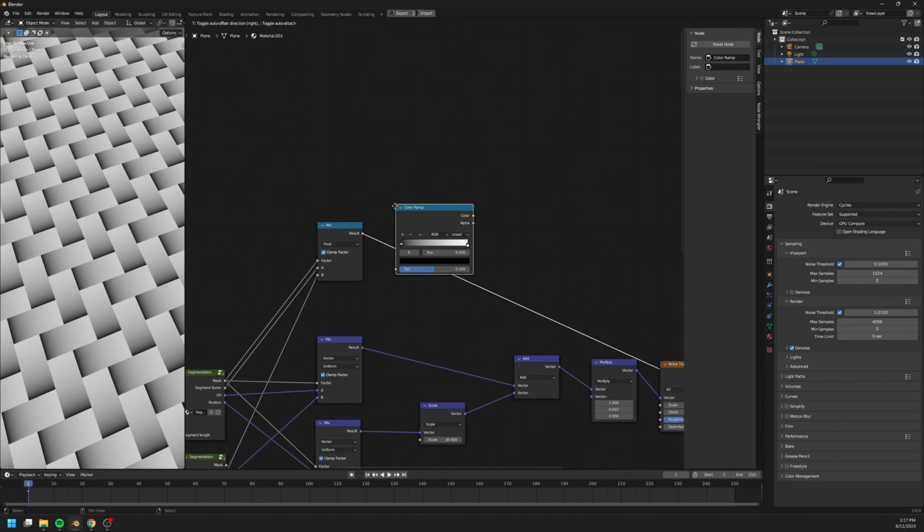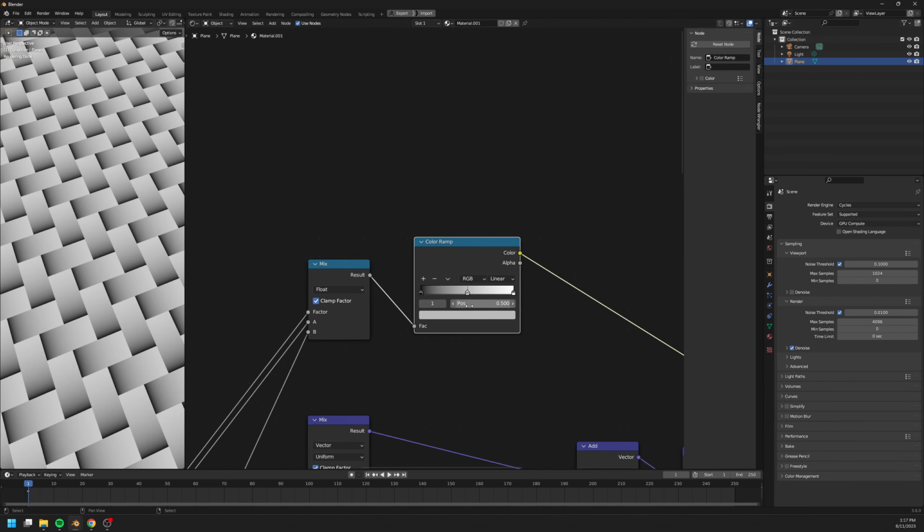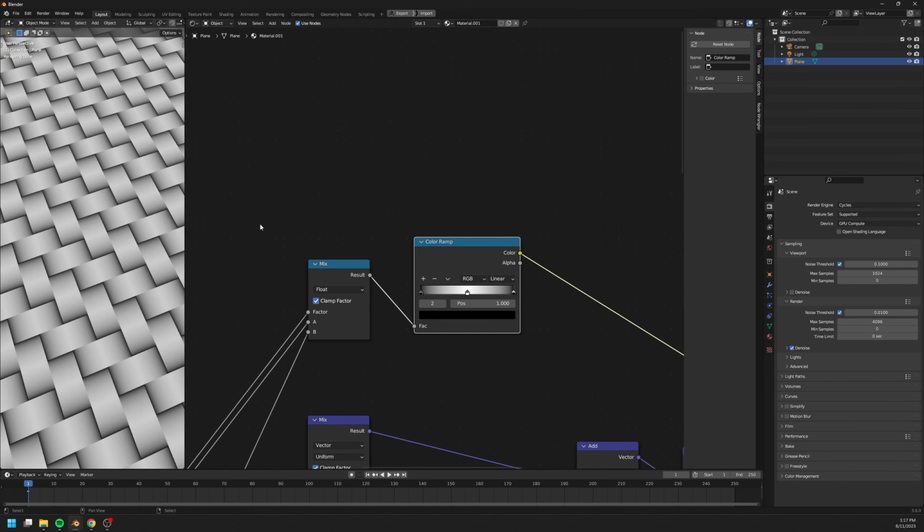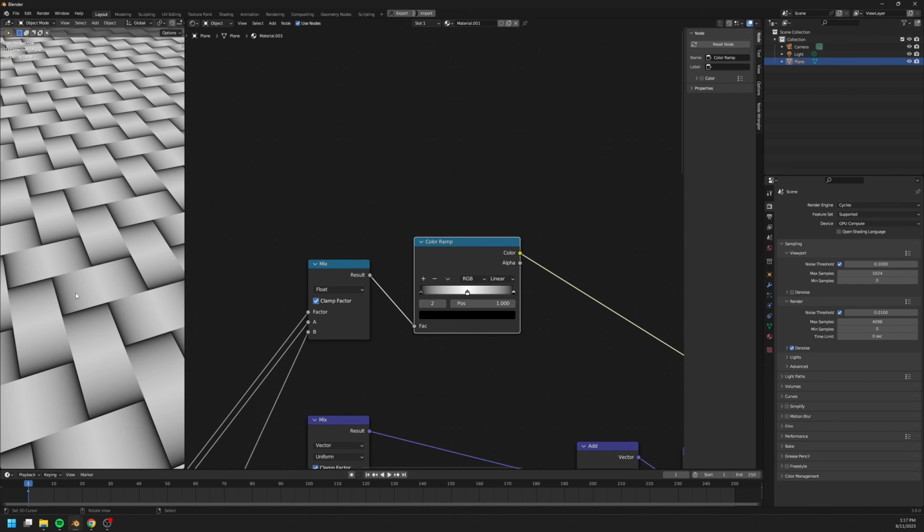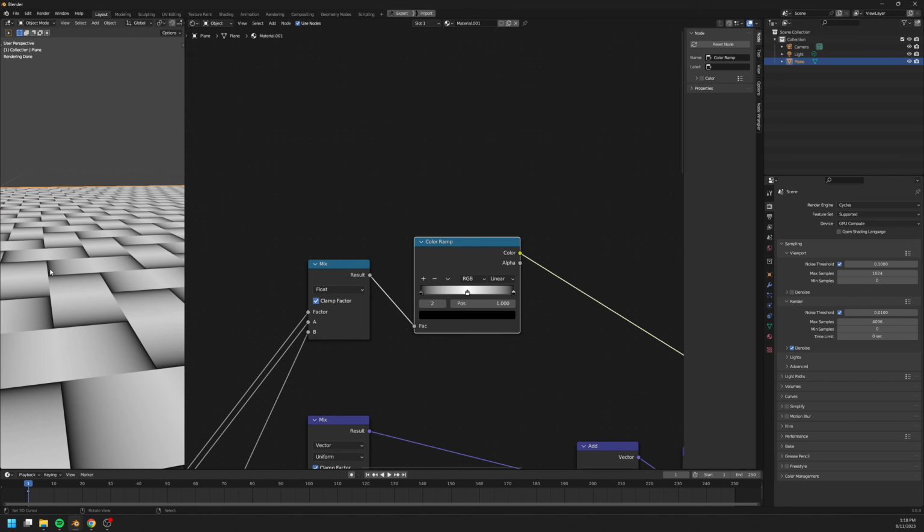And the easiest way to do that is using a color ramp node. Create another key at the exact center, and this key should be white. And set the left and right key to black. Now we have some very nice mirroring gradient, but if we use this to create a bump, it's gonna create a sharp bump like this. We need it to be curved like this, right?